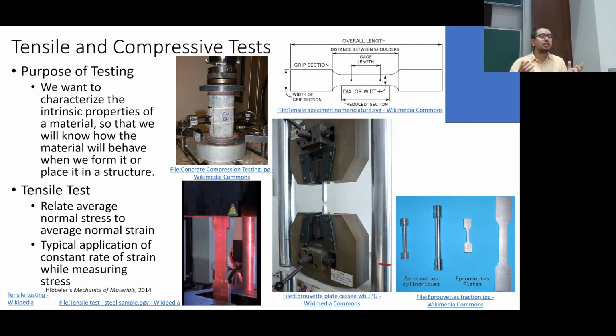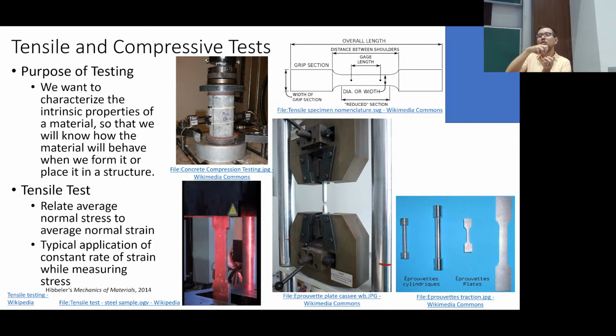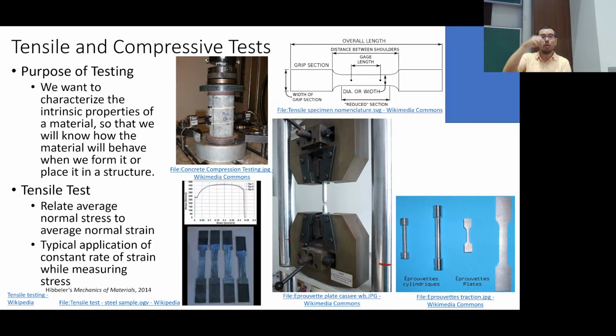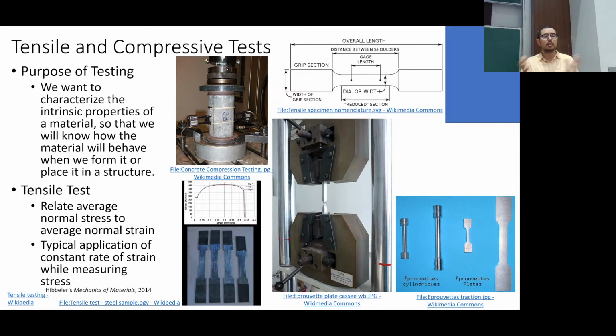So we've talked about stress, we've talked about strain. Guess what? These machines, they tell us the relationship between them for a given material. So as you stretch the material, you already have this intuition, okay, that means that the strain's going to go up. And you also already have this intuition that the force required to stretch the material more goes up, which means that the stress inside the material is going to go up, right? So there's already this idea, right, that as stress increases, strain is going to increase and vice versa.